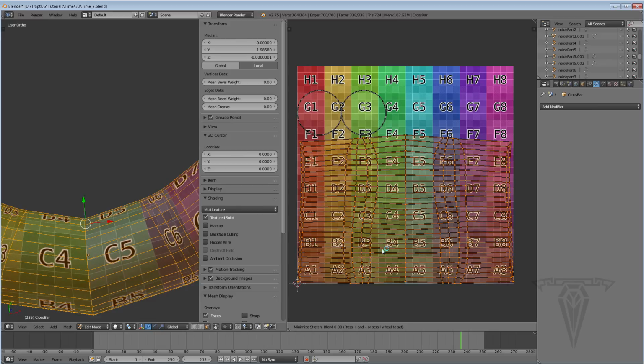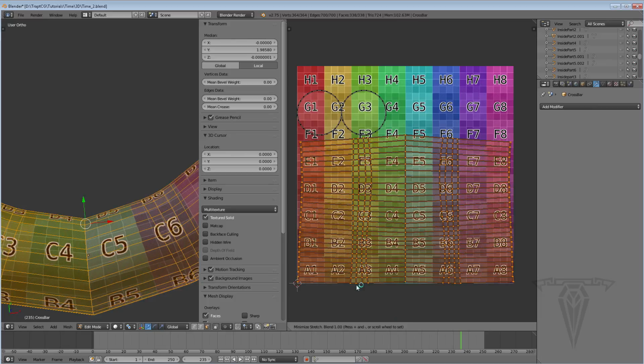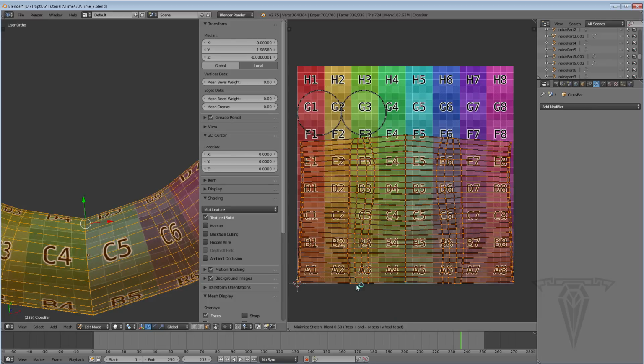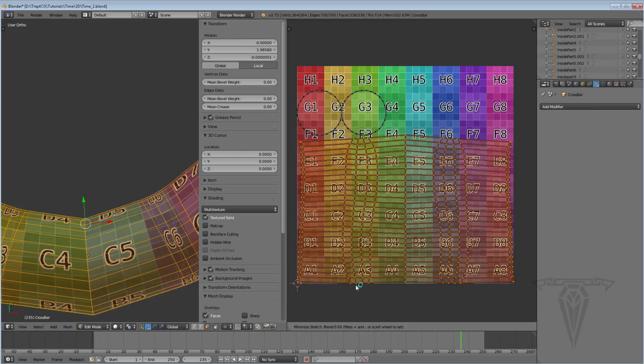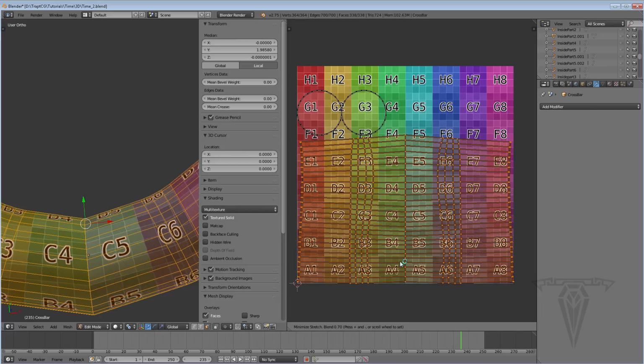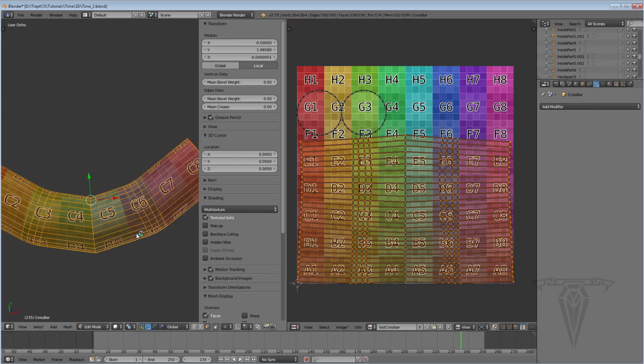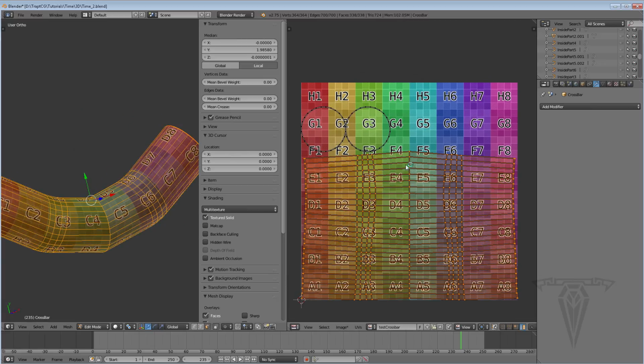Okay, now down here at the bottom you can see that it says 0. Now it also says press plus or minus, or scroll the wheel to set the value. So if I scroll the wheel up, you can see it's changing the squash or the stretch. Down at 0, you can see in my left window that the C is very squished. And if I scroll the mouse up, now it's not squished. So I have to decide where in here I think is going to be best. And it looks like 1% is going to be the best for it. So I'm going to go ahead and click, and it sets it. All right, so that's pretty cool. That's how you can clean that mesh up.